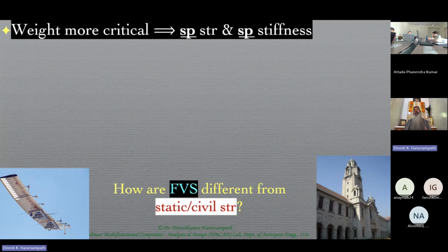So classic examples of that are the kind of materials that are used in the buildings, like let's say steel, and some of you mentioned concrete and reinforced concrete and etc. So these materials have in certain directions, in certain kind of stress conditions, large strength and stiffness, but those are in absolute terms, because when you divide that by the density of those materials, which is very large as well, therefore the specific strength and specific stiffness of the materials which are used in this structure come down.